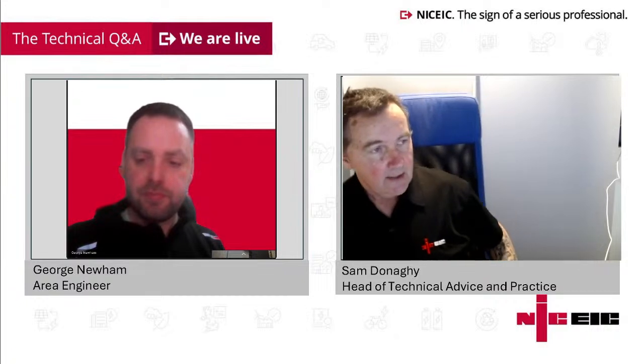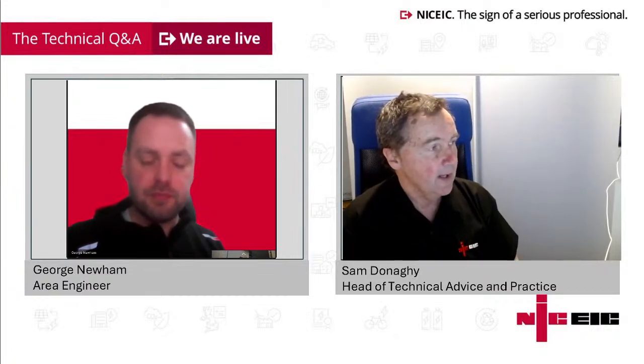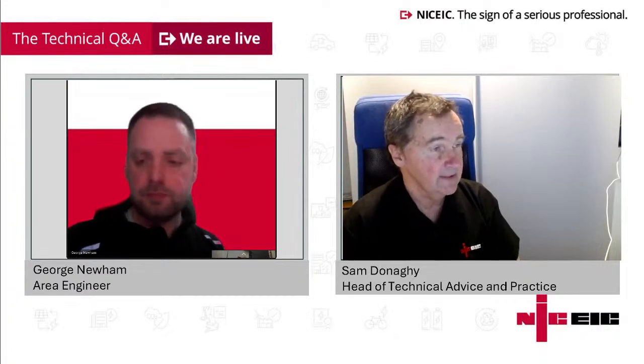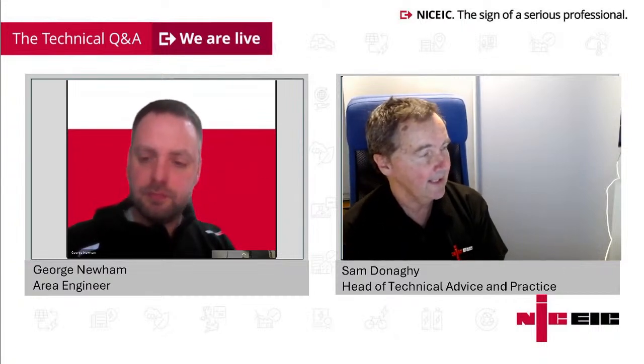It's really a specialism outside of 7671. So you know, it would depend on a thorough review as to whether lightning protection is required based on the location and where it is in relation to other buildings. So for example, if it's the tallest building in that location, then it may need it even though others around it may already have it.